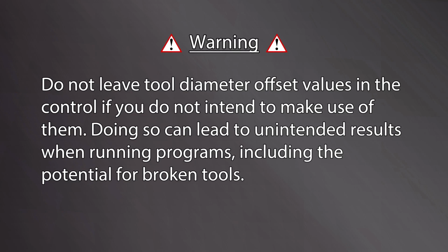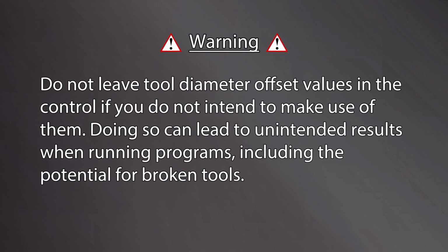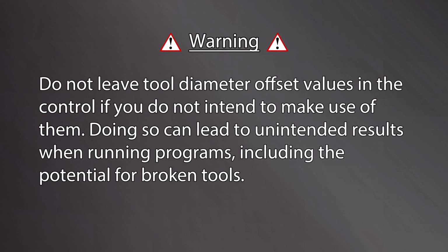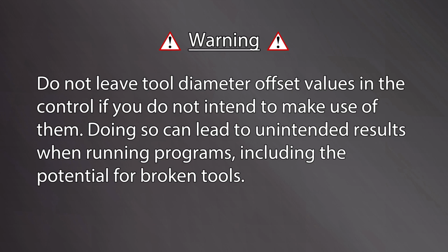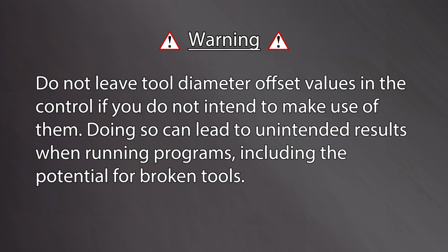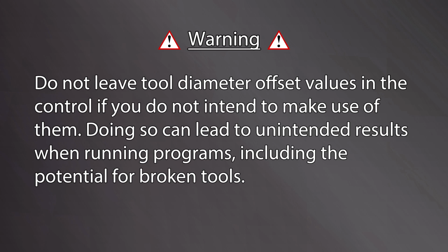Warning: do not leave tool diameter offset values in the control if you do not intend to make use of them. Doing so can lead to unintended results when running programs, including the potential for broken tools.